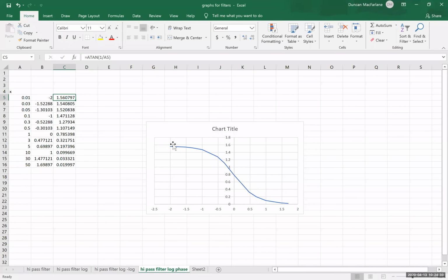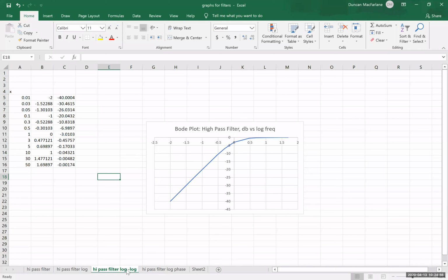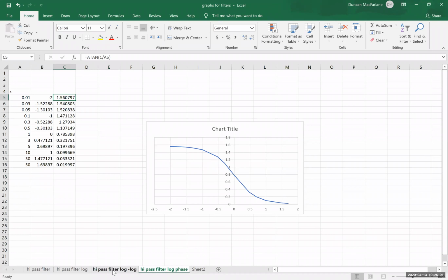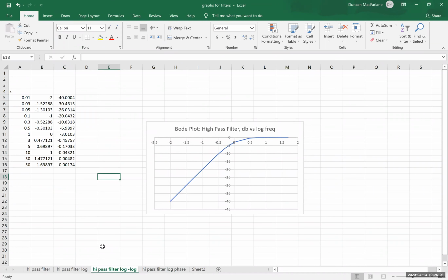So I'm going from a destructive interference where these frequency components cancel out and thus the signal is rejected, to a place where there's no phase response, and I add them constructively and they pass through. So the phase information, if you read it right, gives you exactly the same information as the magnitude response. You just have to analyze your filter in the phase domain, or thinking about the phase of the sinusoid signals versus just what the magnitudes are doing.